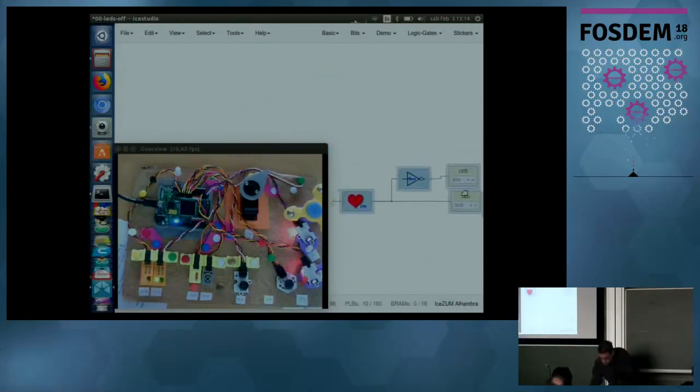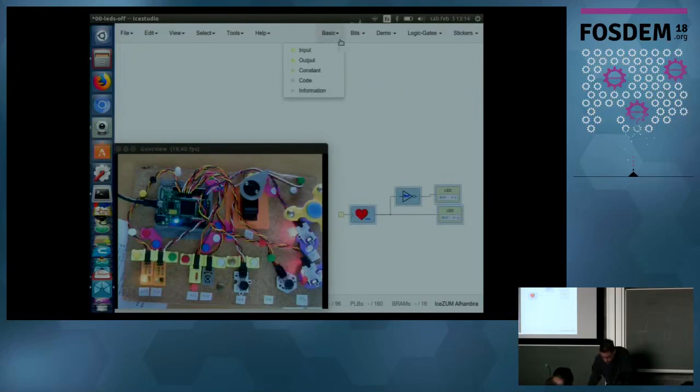Now we would like to work, for example, with servos. Let's move this servo. For moving this servo, I will place here what I call the component a servo bit. This is the simplest controller for moving a servo, only in two positions. If you put in the input a 1, it will move to one position, and a 0 to another position.